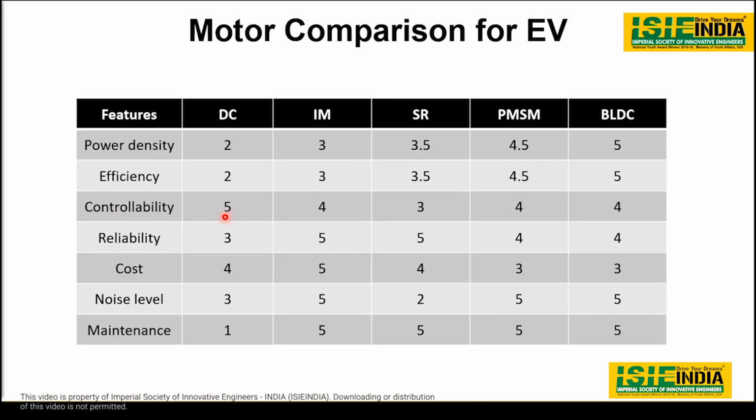At low RPM you need a high torque, and at higher speeds you need somewhat above the base speed, what we call in DC motors below the base speed and above the base speed. In terms of AC, it is rated speed, below rated speed, above rated speed, simply synchronous speed, asynchronous speed, these are the terms. So concluding all these things, controllability is nothing but the speed torque characteristics. In the speed torque characteristics, there is no match to the DC motor actually. That is a clear thing here, right? So the torque and RPM functionality of SRM is very low here.